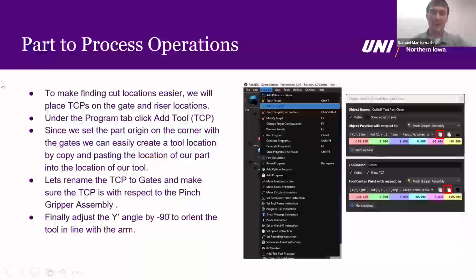All right. Now, to make all of our cutting a little bit easier, so we can move our robot by ourselves, we can set it visually and just eyeball it in our robot cell, but that's not a particularly accurate way to do things, especially with some of these castings. We have some built-in tolerances where we don't want to line it up exactly, or based on our stops, we may not hit our location just due to defects on the casting, say with either flash or a large piece of burnt-in sand. It may shift where our part is being grabbed and moved at all times.